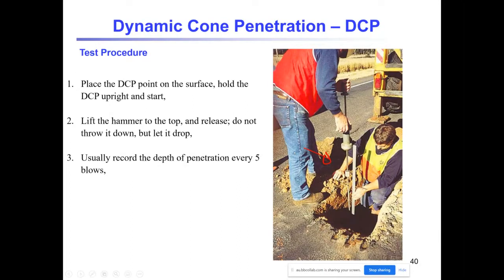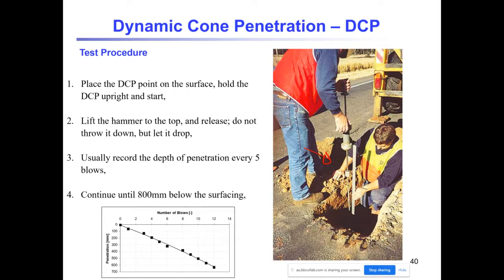And we usually record the depths of penetration every 5 blows. And eventually you get the results like this. We generally continue the test until 800 millimeters to 1 meter below the surface.